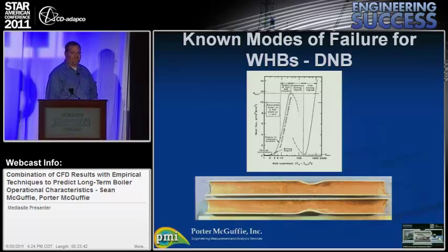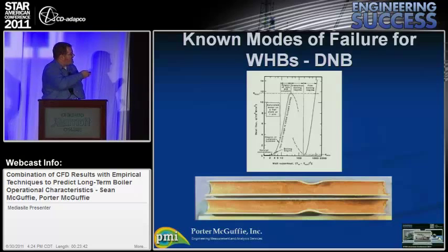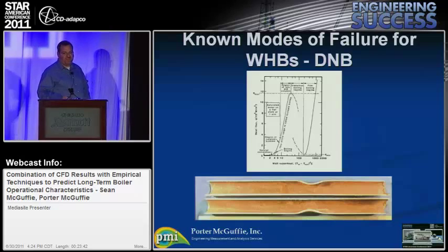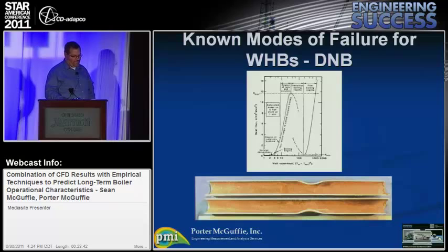If your temperature gets up into the 1100 to 1400 degree Fahrenheit range with our 500 to 650 psig boiler pressure, we will reach short-term creep failure, which we see on the tubes on the bottom portion of the slide. And this tube dimpled in, and it's known from operation this occurred over about a 10-minute period. There's actually a crack that doesn't show up very well in this image, but that was a loss of pressure boundary. You started to flow water back into the thermal reactor. The water starts contacting the refractory, which is at 2800 degrees, and really bad stuff happens very quickly.